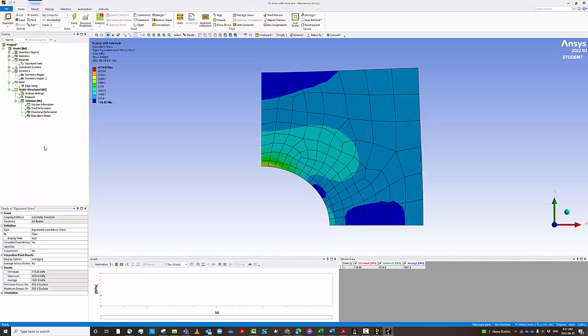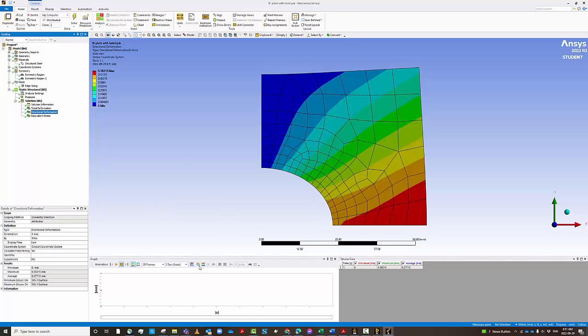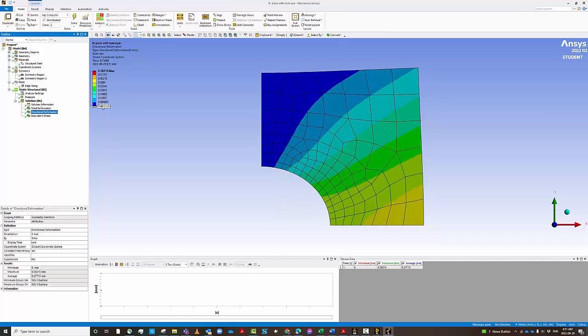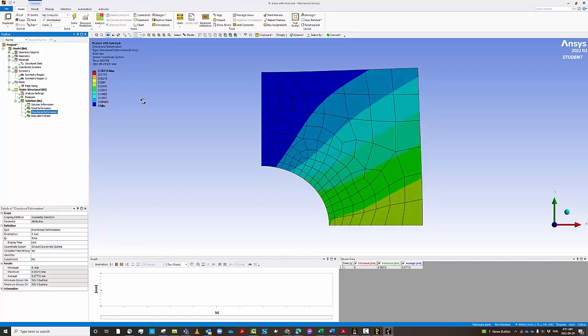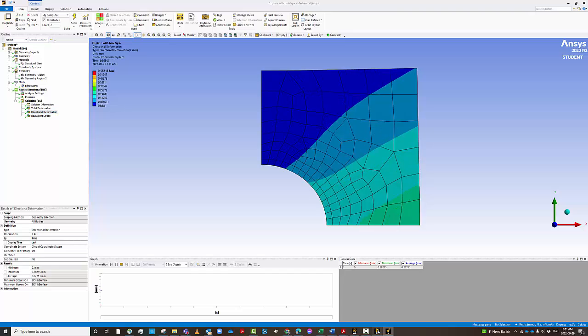Okay, you can, of course, here go to these graphics, show it to people who don't know what finite element analysis is, and wow, you are creating rocket science, but it is not really rocket science. It is graphical. One of the things also that you need to keep in mind when you look at these results is that this is a graphical representation. So the values here, you see what is the deflection here? The maximum value of the deflection is 0.5 millimeter, right? It might look huge here with this red number, but you have to look at the numbers, because this is a graphical representation.